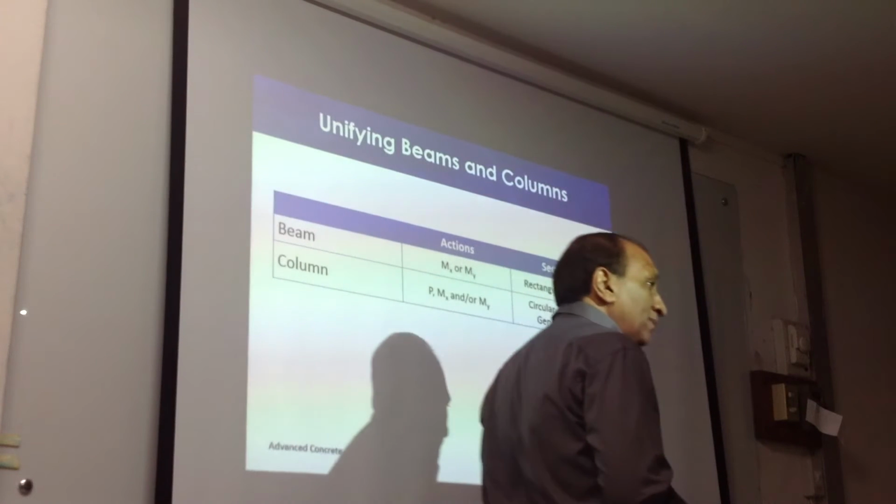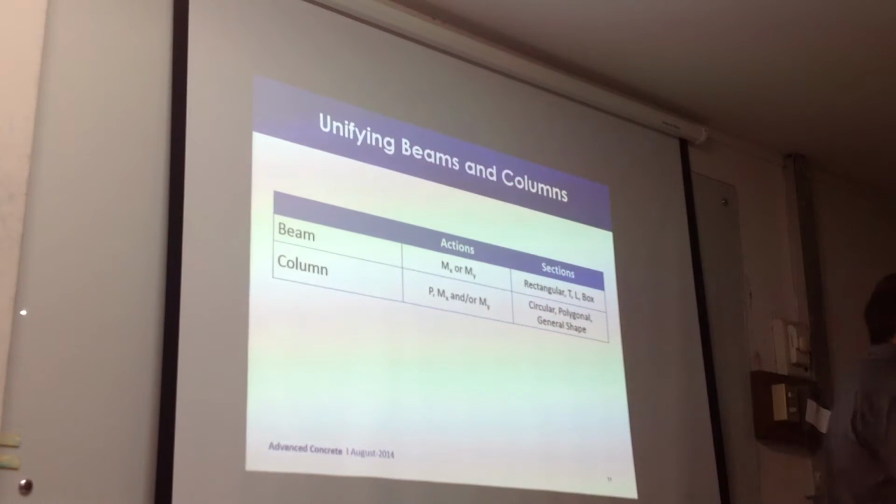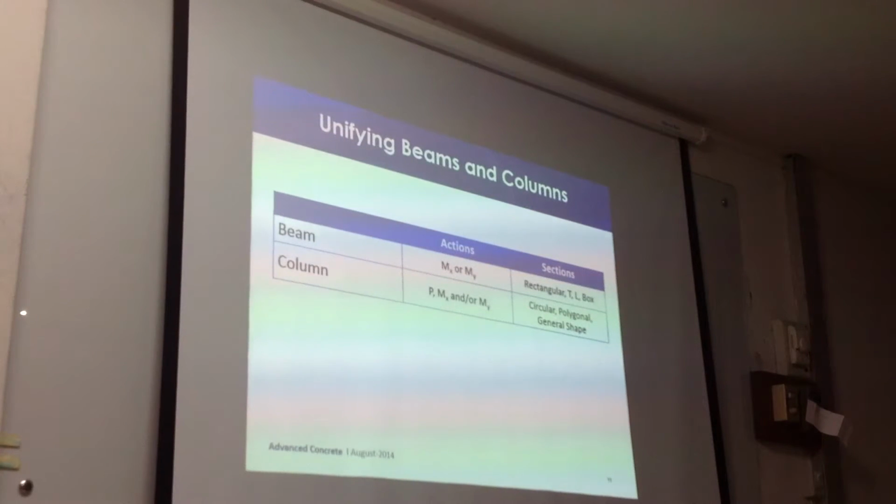What is the difference between a beam and a column? What is a beam and what is a column? How do you understand? Beam is flexural and the column is compression. The basic definition is absolutely wrong, right? Because a column is an axial flexural member. It has both bending moment and axial force. So dominant forces are not necessarily so. Moment can be dominant in a column, in a small low-rise building. You have absolutely no idea, or you cannot define it at all.